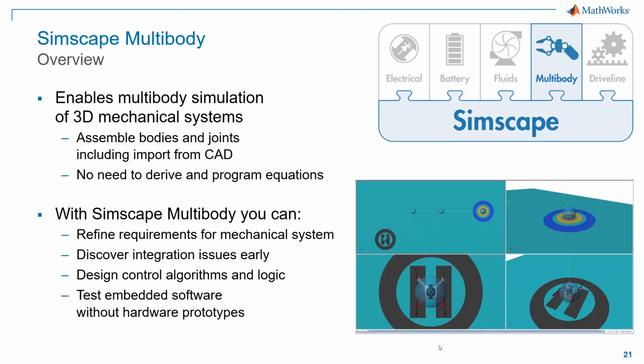There are different approaches. If you want to solve a certain problem, you can have multiple approaches. Another approach which people use is the multi-body approach. For example, you have created something in CAD, and I'm pretty sure that all of the teams participating in this competition, even when I work with automotive competition teams, need some kind of CAD assembly of your design. So in that case, what to do? If you have a CAD assembly for your quadcopter, can you do some kind of dynamic simulation? Yes, you can. That will be a multi-body approach.